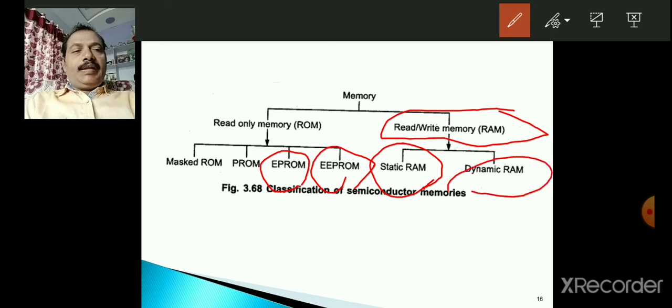Whereas in the dynamic RAM, though the power is on and everything is fine, the data leaks and slowly disappears after a certain time because the data is stored in capacitors, which discharge. That problem is eliminated with refresh circuits, by reloading the same discharged amount of charge, recharging it once again. So that is a dynamic RAM.